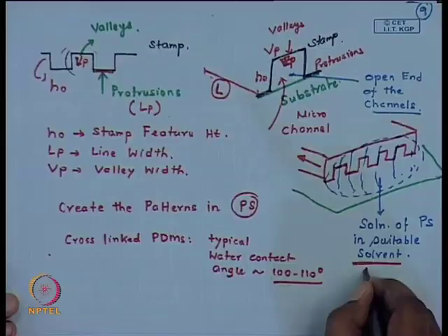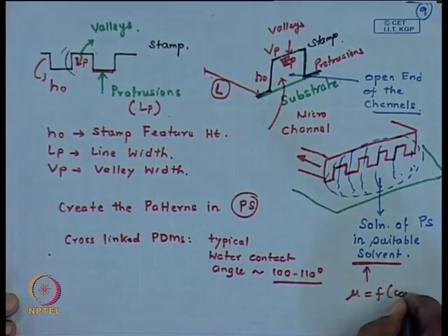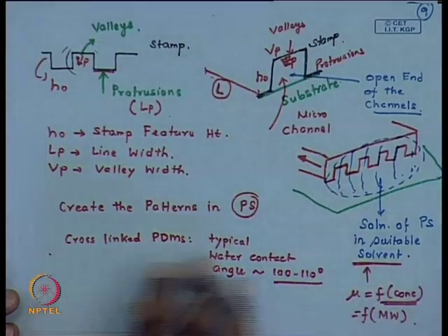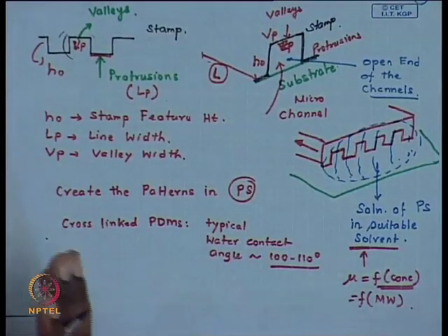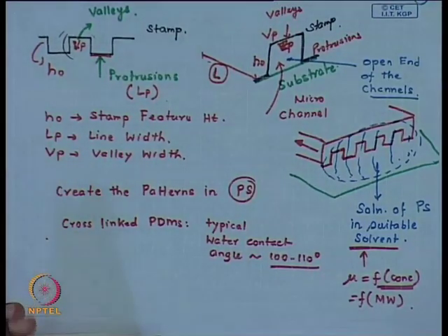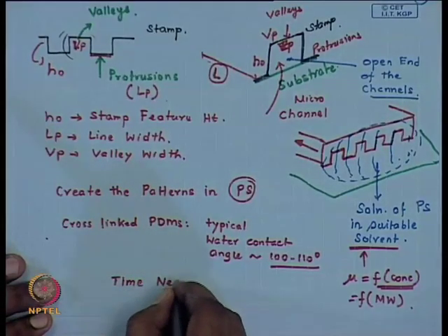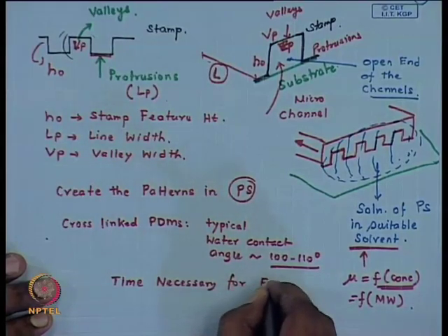Depending on the viscosity of the polymer solution you have taken, and viscosity is going to be significantly a function of the concentration of the solution as well as the molecular weight of the polymer, the viscosity is eventually going to determine the time necessary for filling of the channels.